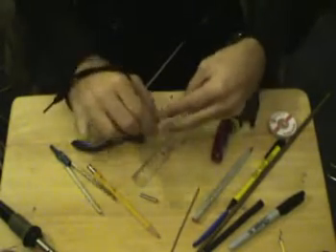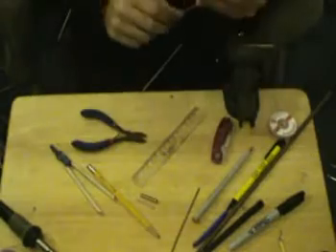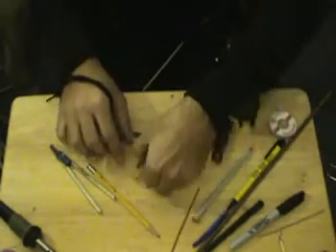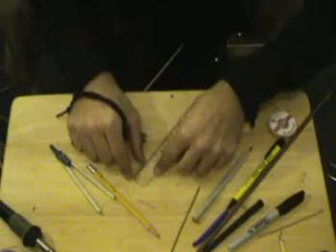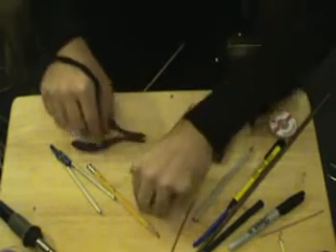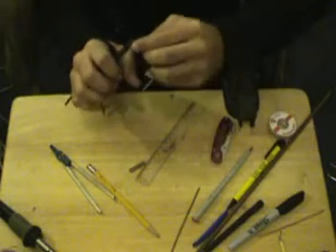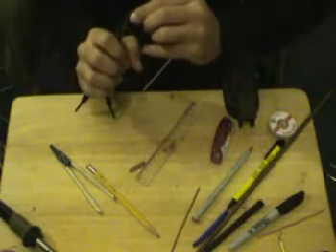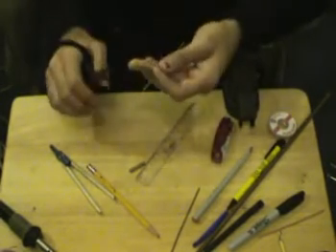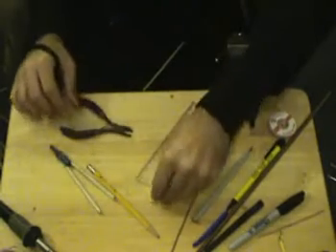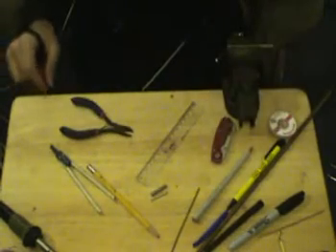Now, whenever you're making something for 2.4 gigahertz, try to stay as spot on to your measurements as possible. So, having a hand file around and actually filing things down to the closest millimeter is a good idea. Personally, I tried to be less than half a millimeter off, but if you are, it's really not going to kill you. It'll probably could kill your Wi-Fi card, but that's besides the point.